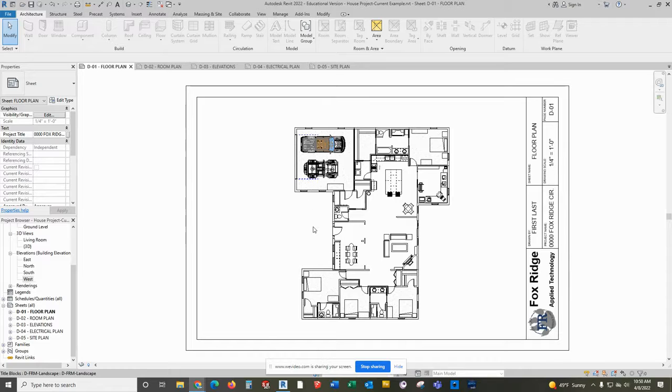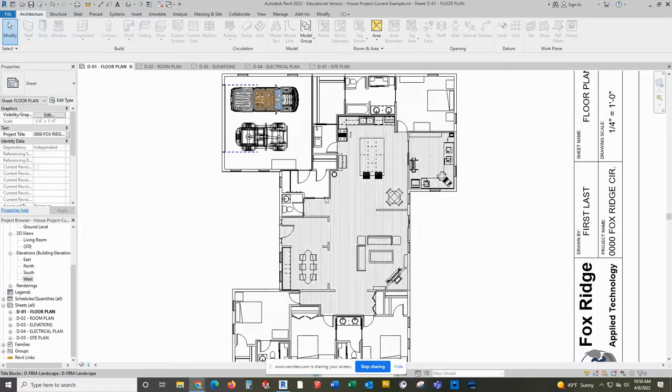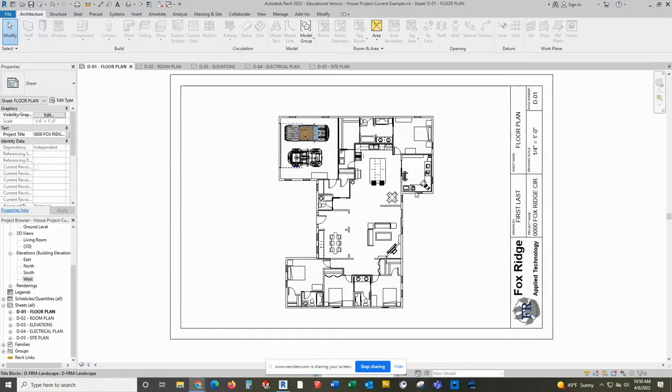what you don't want to do is hide all floors. Okay. I know in this view it's a little zoomed out, you can't really see, but if I roll in even just once or twice, you can start to see the wood floor and the carpet patterns come back in. Okay. And we want those there, and they will be there on your printout, even if you're zoomed out a little bit and can't see it right now. Okay. But we do not want to see your grass, your porch, anything outside the exterior walls.